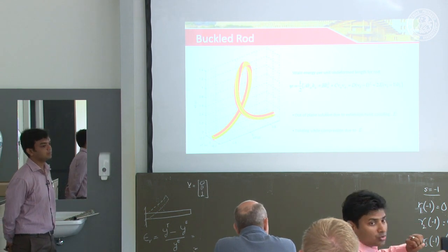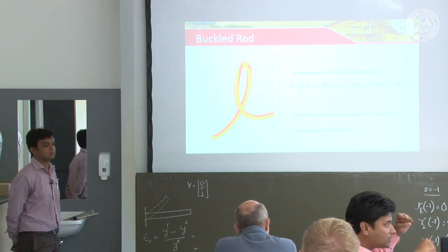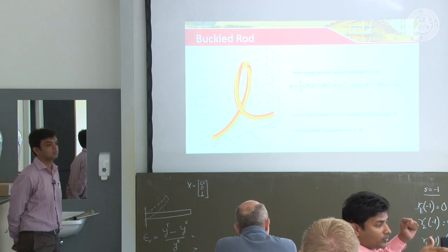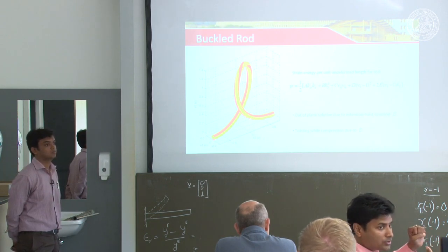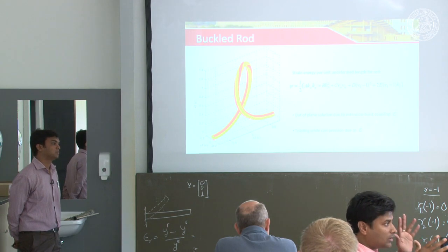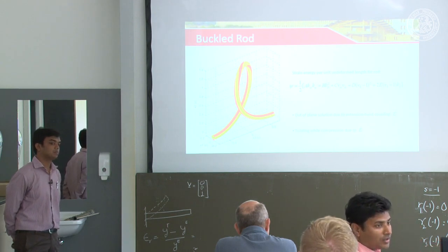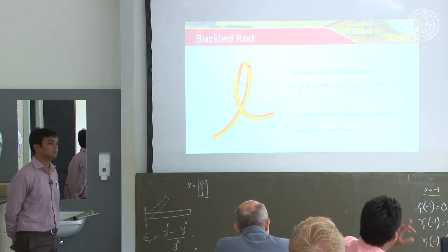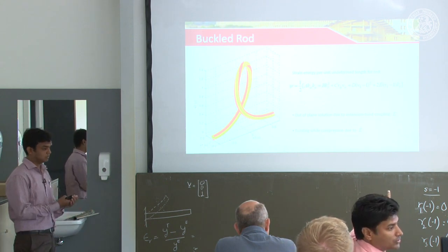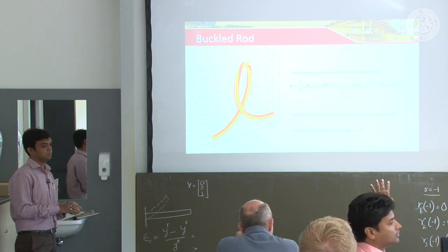If you have an isotropic beam, for example, you stretch it, it never twists. But if you have intrinsically twisted beams, if you stretch it, it's also going to twist. So that's a very interesting effect. And to model that effect, that extra term is introduced, which models the coupling between extension and twist.